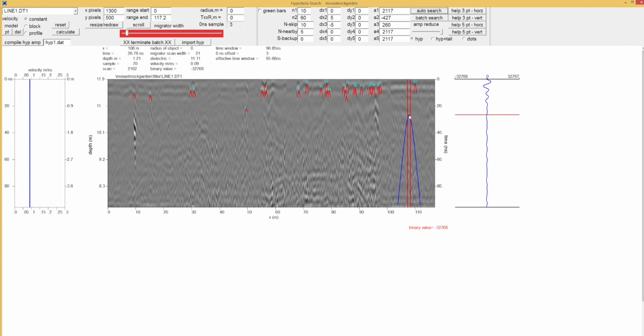For instance, if your reinforcing bar is corroding in a particular area, then it might not be capable of reflecting the radar signal as well as some other areas. So it's a very quick way of creating essentially a map of the reinforcing bar deteriorating.